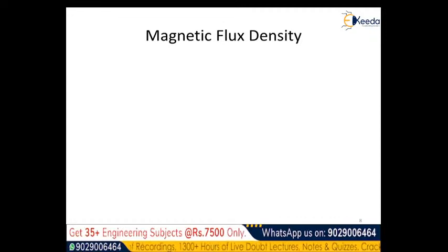Now the magnetic flux is there in the phi direction. It is a plane in the horizontal orientation, and if we have the field in the phi direction, a plane that is perpendicular to the capital B representing the magnetic flux density, it will be in the region inside. Hence we have to consider the rho dimension ranging from 0, meaning the point on the z axis, to 2 millimeters, meaning the periphery of the current carrying conductor of cylindrical shape. So rho will be 0 to 2 mm, and z will be from 0 to 1 meter, because in the problem statement we have been provided the length of this current carrying conductor, which is 1 meter.